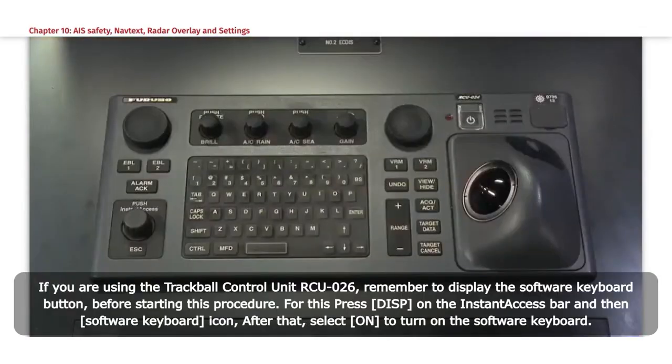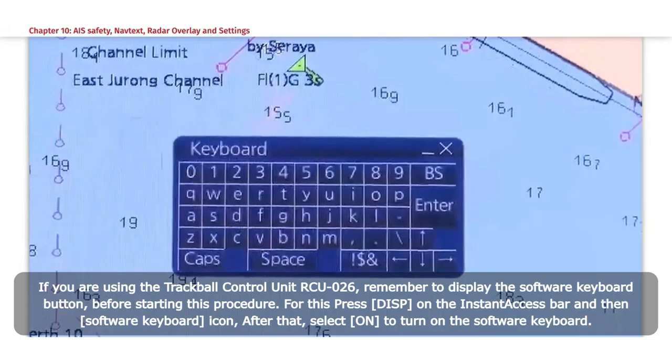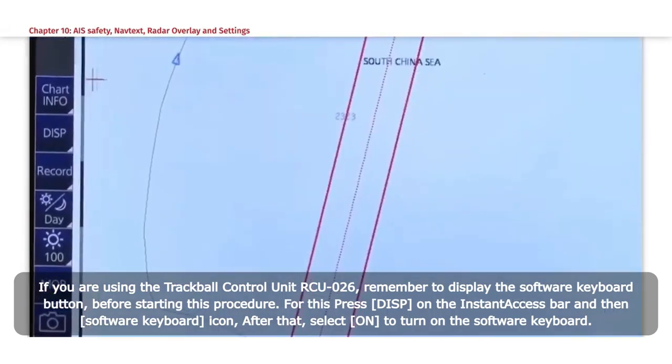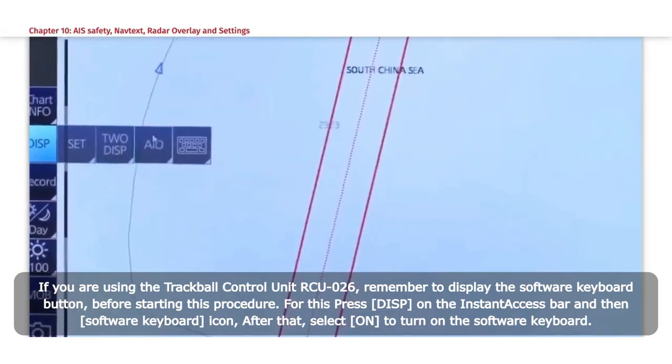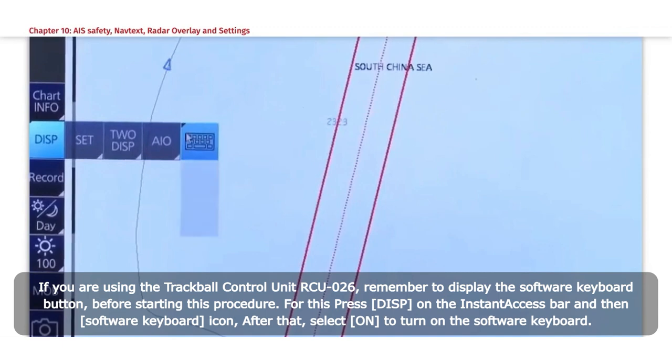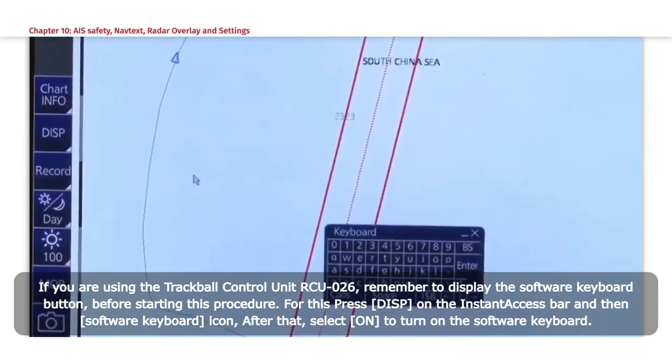If you are using the Trackball Control Unit RCU026, remember to display the software keyboard button before starting this procedure. For this, press DISP on the Instant Access bar and then the software keyboard icon. After that, select On to turn on the software keyboard.